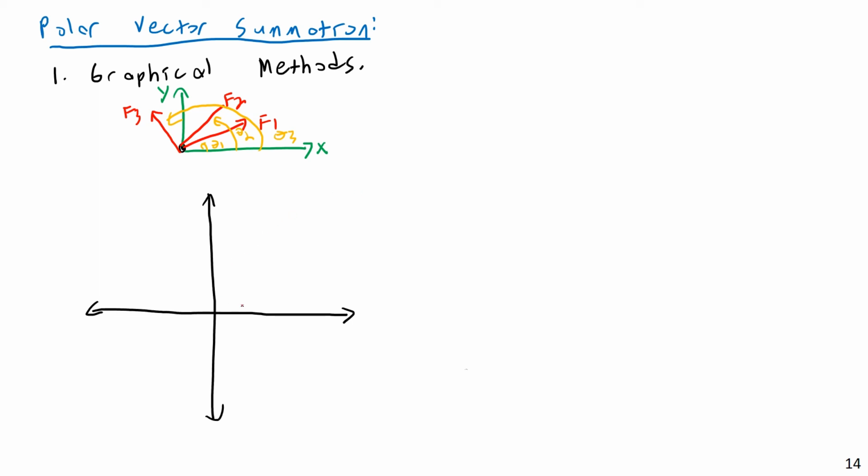You really need to use a protractor and a straight edge, and not just a straight edge, but a ruler to measure these distances properly, because, now this is unstated from my previous videos, there is an unstated thing in all of the drawings I use throughout my entire courses, and this is very common in all sorts of science and engineering courses, that I never really draw my drawings to scale. It's not really important for most of the things I do, but if you are using a graphical method to solve a problem, scale is everything. So you need to make sure everything is to scale. And so that's the real pain.